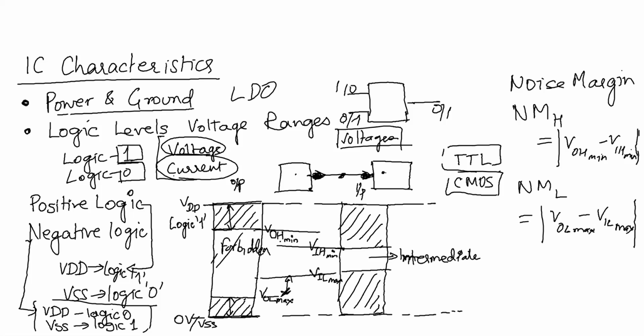And if you talk about these logic levels for TTL, I'll take just one more minute and I'll wind up. For a 5-volt TTL system, this is 2 volt and this value is 0.8 volt. No, I have not said it correctly.